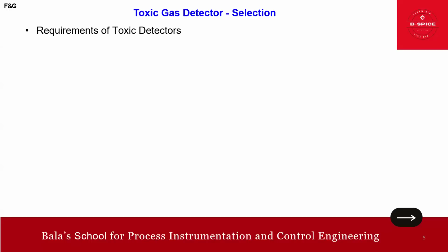And when we talk about the diagnostics, of course, the same: close to minimum signal level, low voltage, internal system failure, failed to zero, calibration error, all these we need to ensure. And you may ask, what is the standard actually applied for this? Yes, the toxic detector shall, as a minimum, comply with the requirements in line with EN 45544. All sections of 45544. Okay, so that is the requirements.